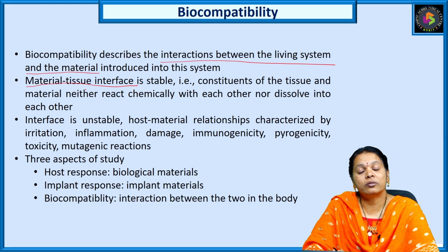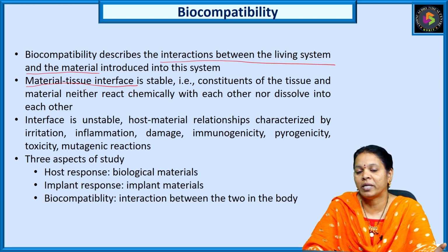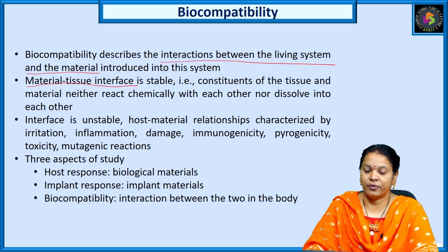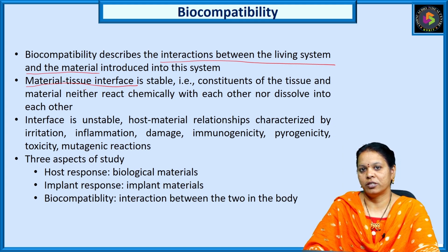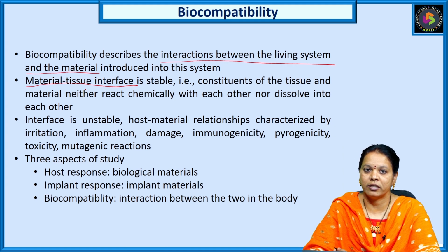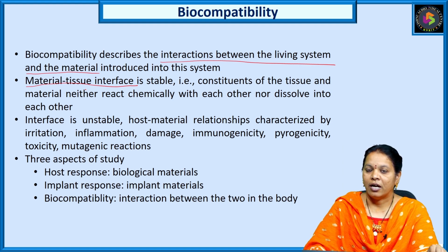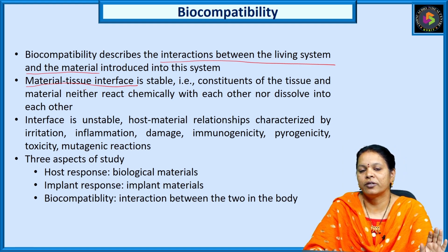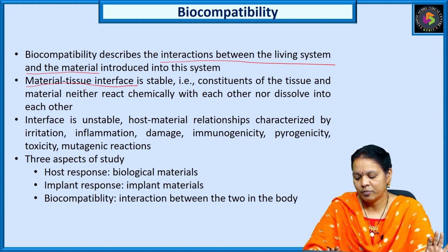So therefore, in order to analyze the level of biocompatibility a material offers for it to be selected for a given application, we need to study it in three different aspects. One is the host response, that is the tissue response with respect to the biological tissue, which is coming in contact at the interface. And the other one is the implant response with respect to implant characteristics, properties, and all those things. And finally, biocompatibility will be evaluated by studying the interaction between this biological tissue as well as the biomaterial.